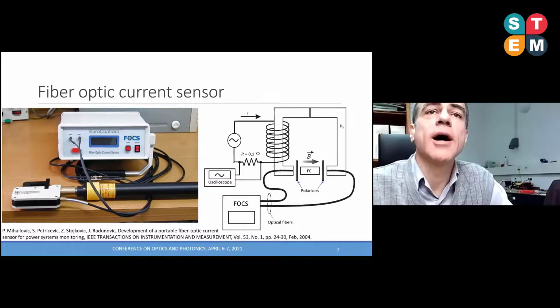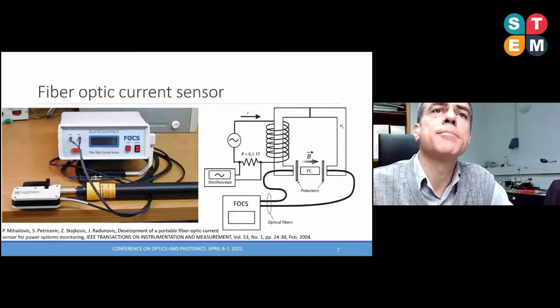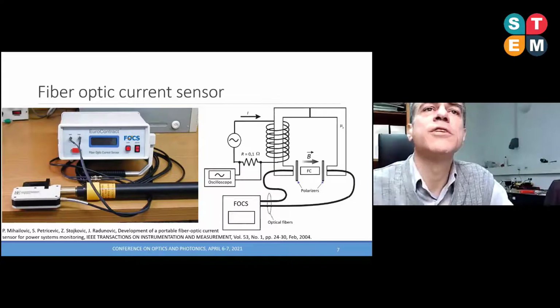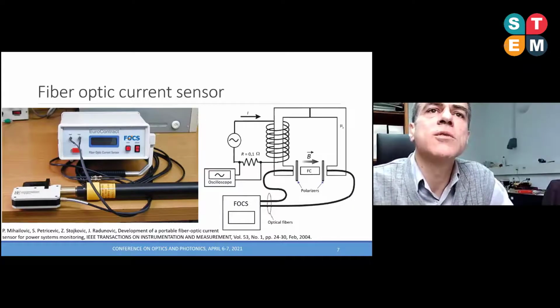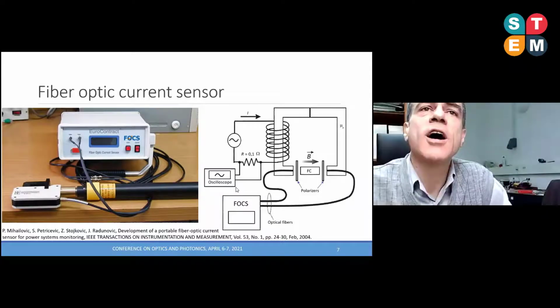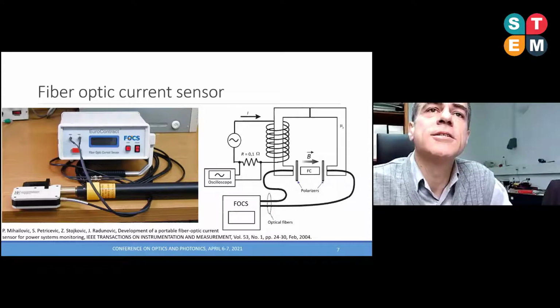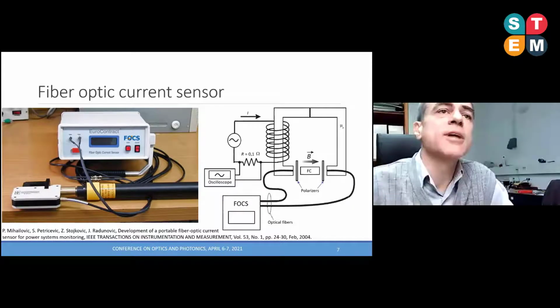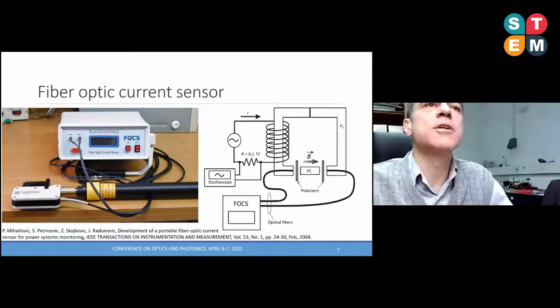So the idea of this magnetic concentrator is to increase modulation depth and to suppress the influence of nearby conductors. Well, you can say that we lost a lot of the advantages I claimed earlier, but note that we saved a high frequency range for power systems, and that was our goal for this sensor. So basically we can monitor the first 25 harmonics, and that is sufficient for power systems. But this sensor is also not in wide use.